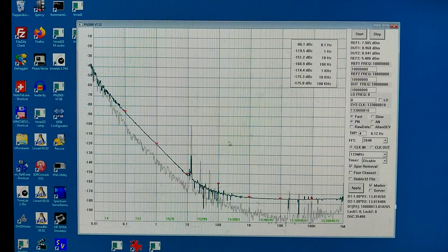The measurement time is about 20 hours for this, and I can see it is a good straight line down to 0.1 Hertz, 0.01 Hertz. It has not converged, but there are no circles here, so the result is about minus 47 dBc per Hertz at 0.01 Hertz. And I can see the curvature when coming very close to the carrier.